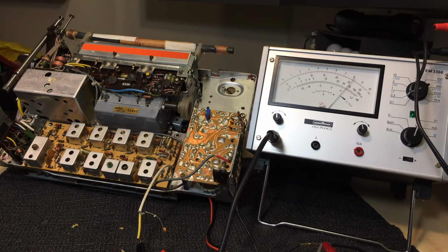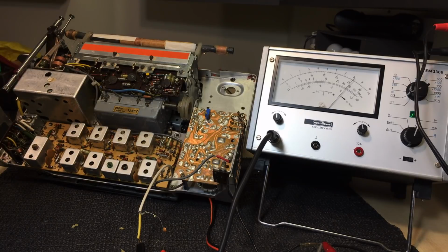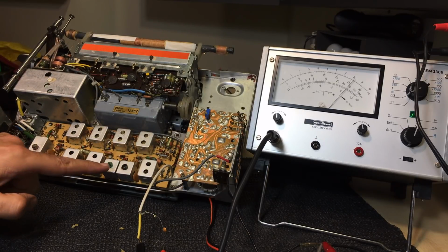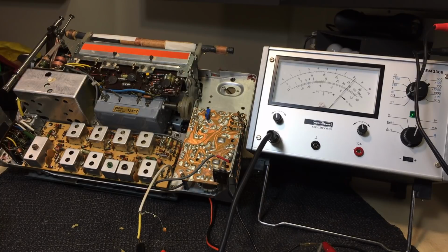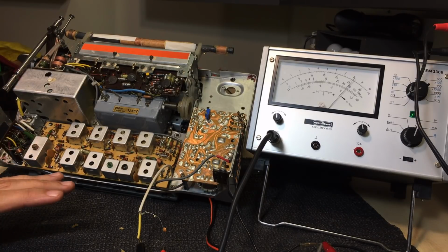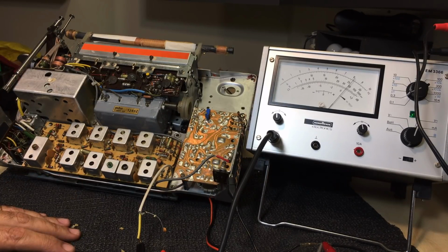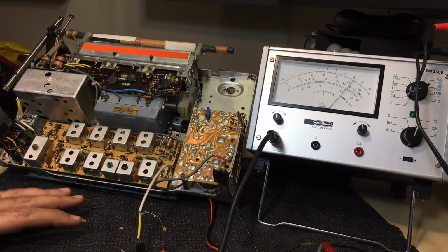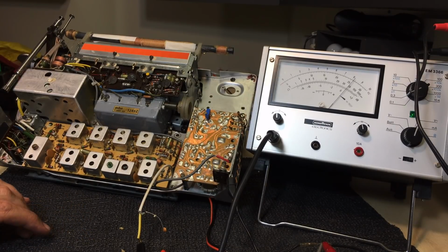Not much to it once you've understood what it is you're doing and why you're doing certain things and why you have to do a different way. I suppose now if I put the scope on there, I could probably get my signal, which before was so low I couldn't read it. And the reason was these guys were misaligned. And I don't understand how they managed to do that. I don't know how these guys were misaligned so much. I think perhaps this whole radio was actually tuned, aligned to 453 or whatever it was, instead of 455. And I'm not sure why.